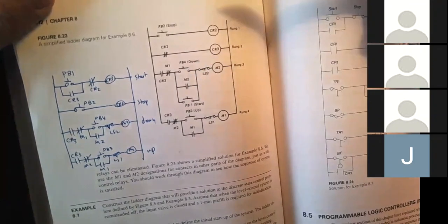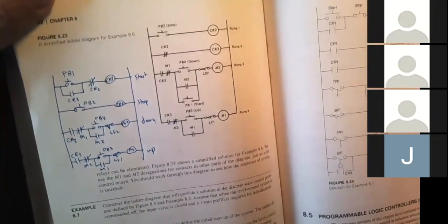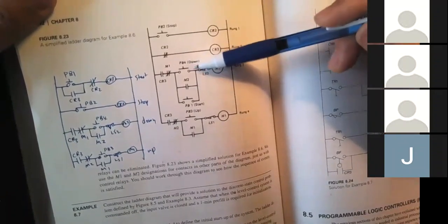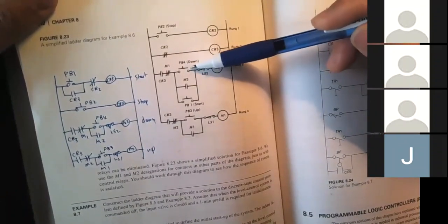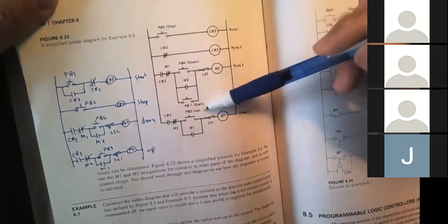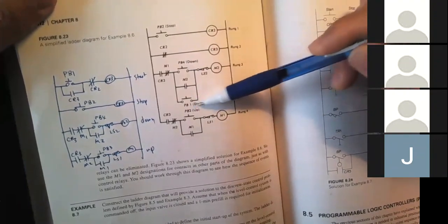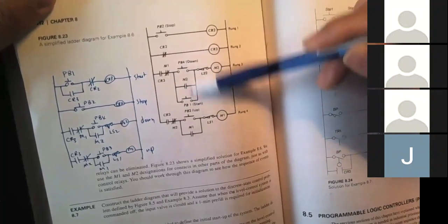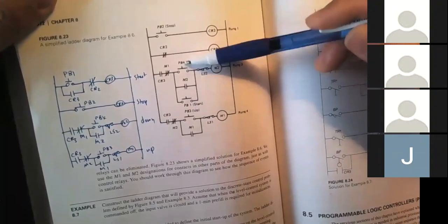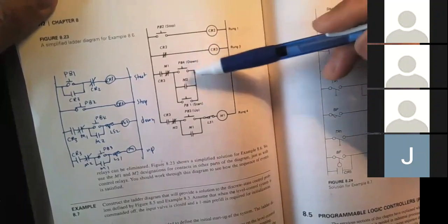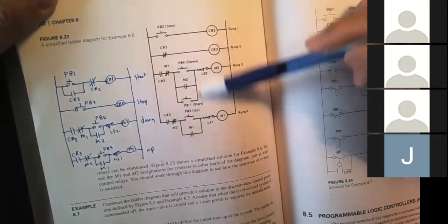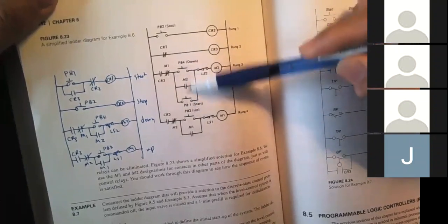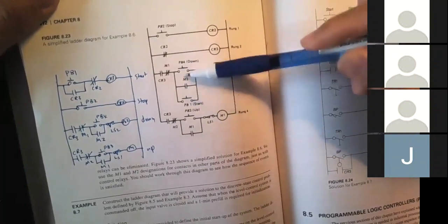As an operator, when I push start, I just want to turn the power on. I do not want the motor to move down, because now it's the identical function. Actually, pushing start and pushing down is the same thing. Why do you have 2 buttons which are basically the same? I consider this, if not a good design, potentially dangerous. If not dangerous, it's not that good.